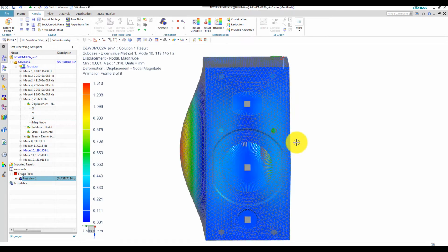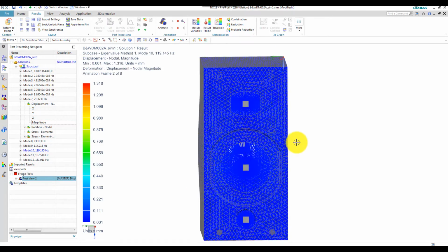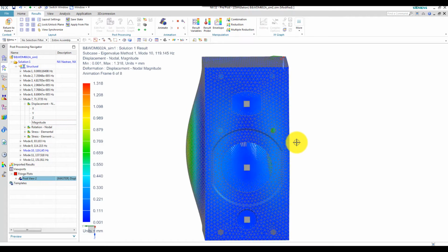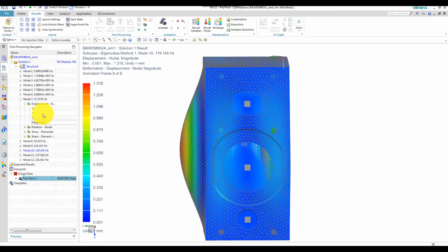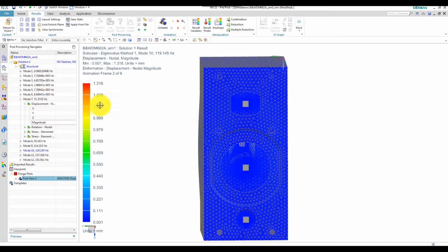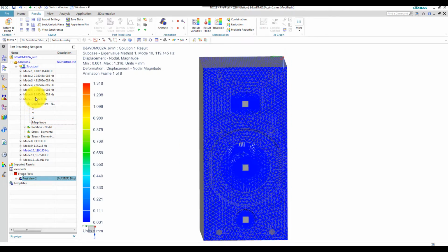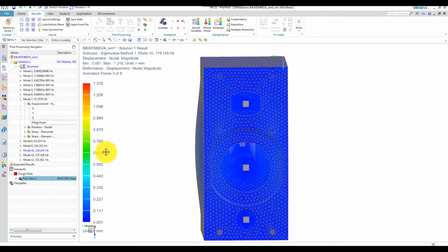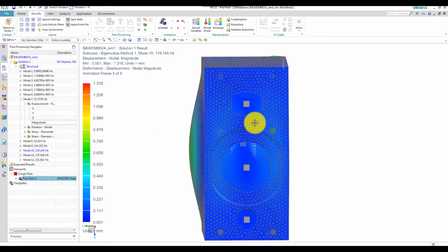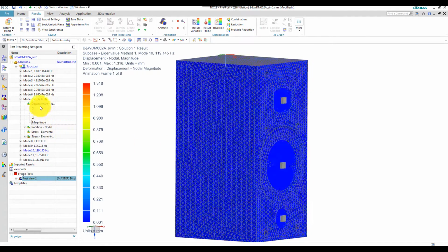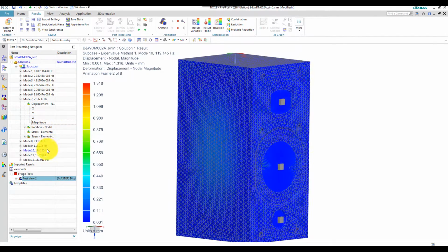But then again, that's the same conclusion and the same thing we had to do in order to increase the first resonance frequency of roughly 71 Hz. So if we reinforce the side walls, we will increase the eigenfrequency number 7 and 10 in the same run. And if we reinforce the front and rear wall, we will increase the other eigenfrequencies.